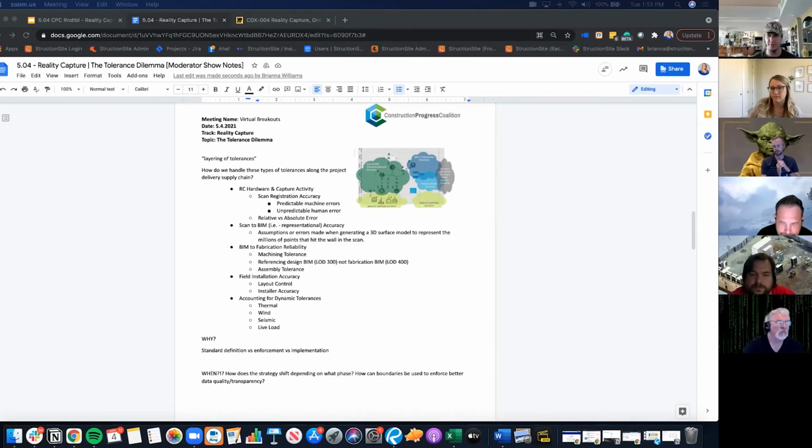But for something like you were describing, Thomas, it's the relative accuracy. Ultimately, you want to make sure that weld gap is maintained. That's relative, so you can localize to that one spot and get a higher accuracy in that one spot. For something that needs that level of accuracy, after that heater is fabricated, we'll go out and scan it to see deviations between design and the actual fabrication and incorporate that into our installation plan.